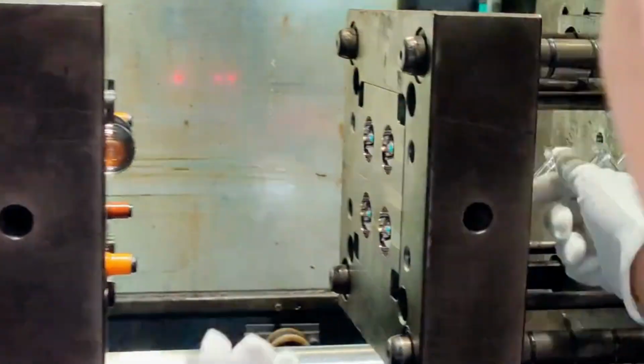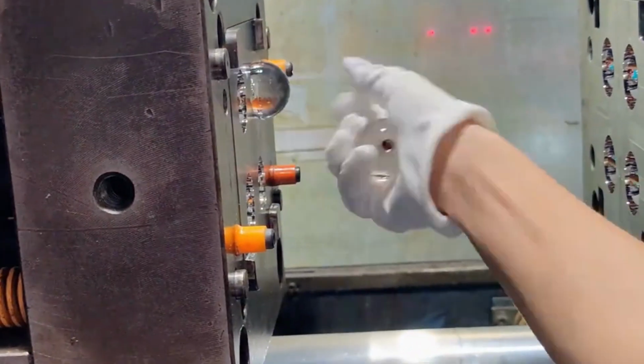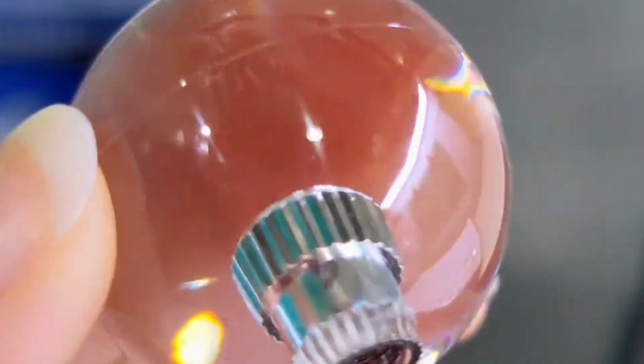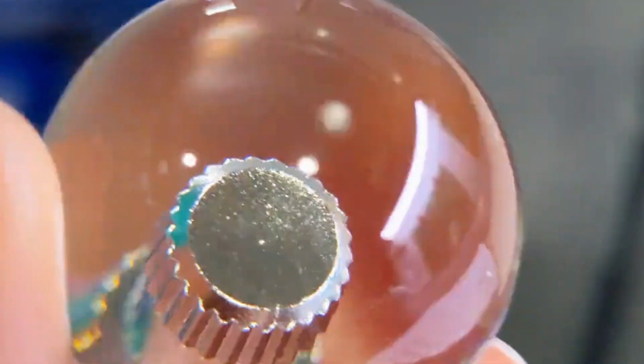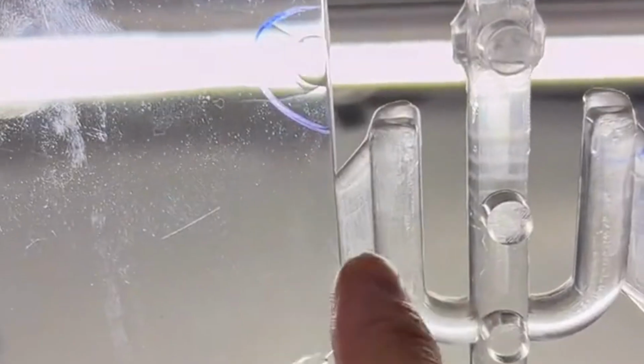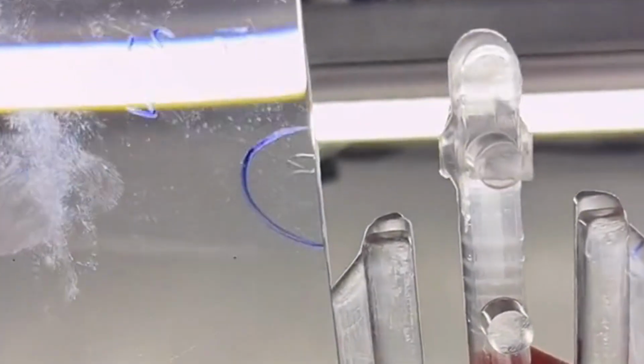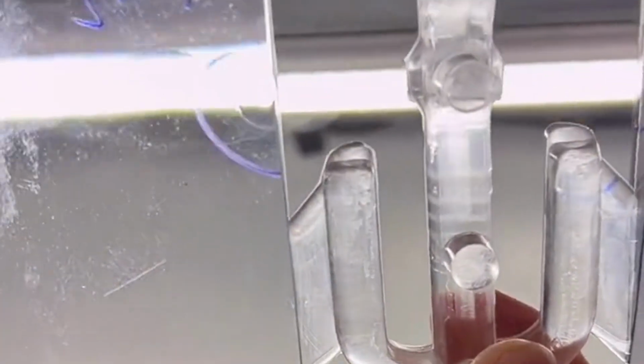The proper injection temperature can make the plastic melt have good fluidity and be able to fill the mold cavity evenly. If the temperature is too low, the poor fluidity of the plastic melt will lead to underfilling, producing flow marks or fusion marks and affecting the transparency of the product. If the temperature is too high, it will cause the plastic to decompose, producing bubbles, discoloration and other problems.